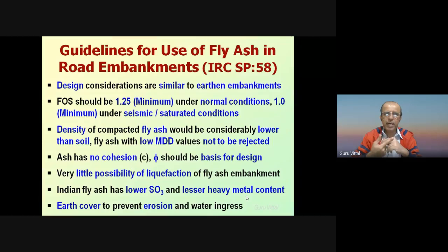Now, some salient points which I have taken from IRC SP 58, I have put here. The design considerations are similar to the earthen embankment. That means whatever stability analysis we make, slip circle method, etc., is entirely similar for a fly ash embankment design. Whatever software we use, maybe Geo4 or any other software, the same software can be used for designing fly ash embankments also.